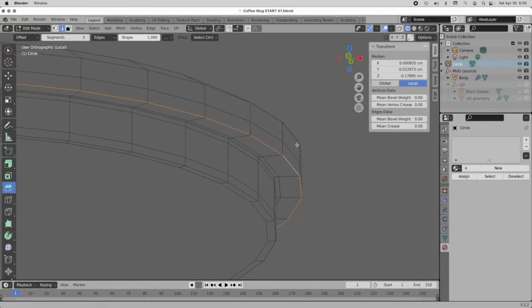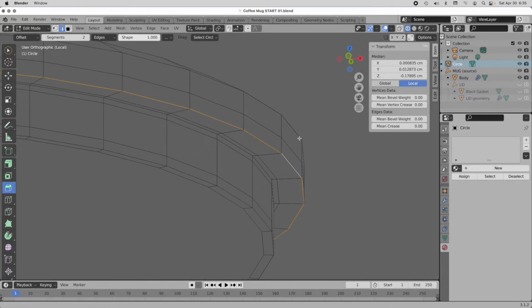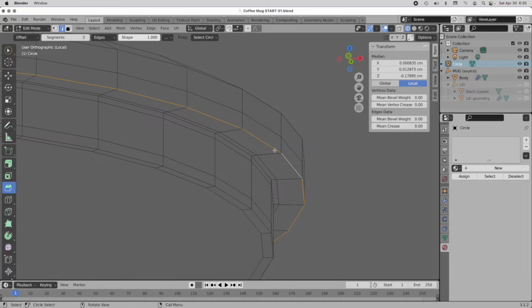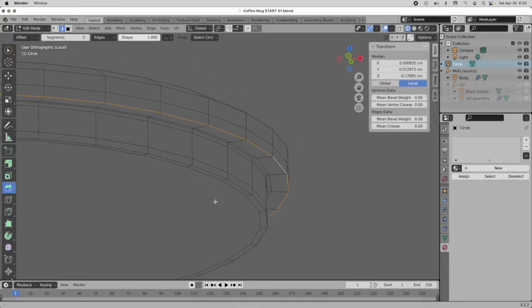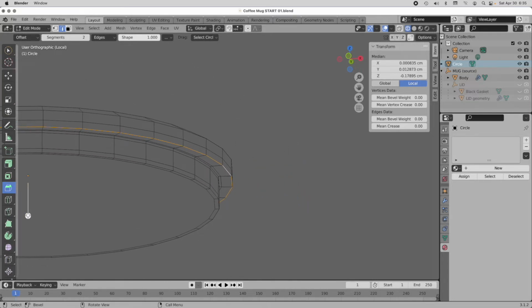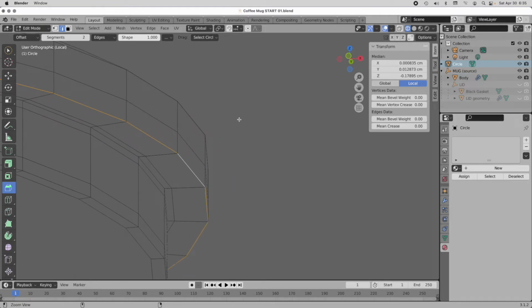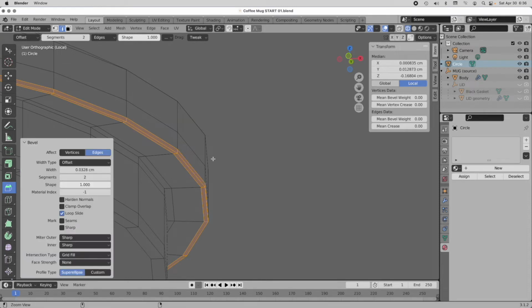Now this is where we want to switch the mode. I want to look more tightly in on that corner right here where my eye is looking, but the widget is way over here, and so this is where we want to switch the mode from selection circle to tweak, and I can just grab that edge and then produce the effect right like that. It may take just a minute of kind of finding where the mouse needs to move, but you can get it right like that. And that'll produce a nice sharp corner.